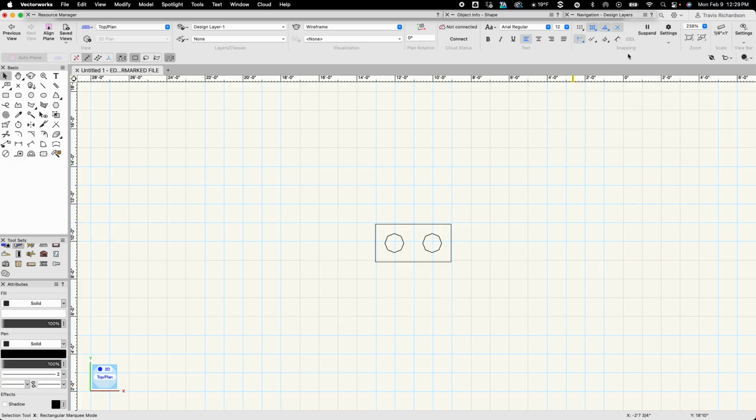Next over here is going to be snapping. This is a feature that Vectorworks has that allows more precision of your drafting. So if I come down to our Lego piece and come right to the corner, it tells me I'm snapping to that endpoint. Or maybe I'm going to come over here and I'll snap to the midpoint of that line, so that when I draw a line to attach that, if I'm on the midpoint, I can click there, and I know that that line is touching that piece of our Lego piece.